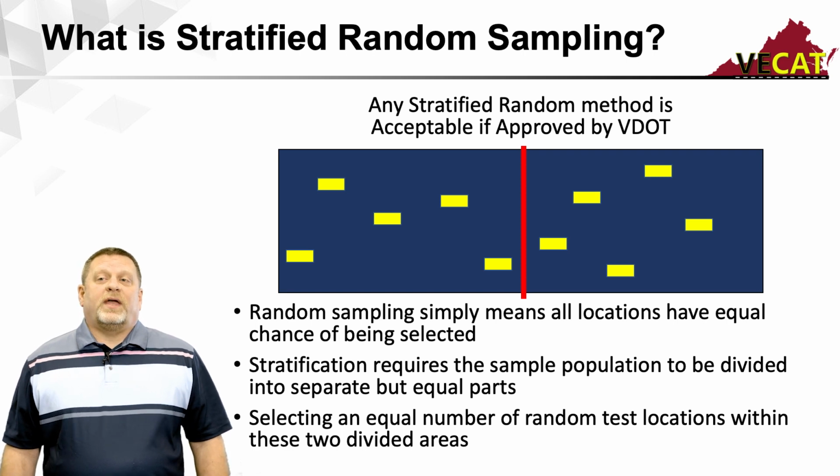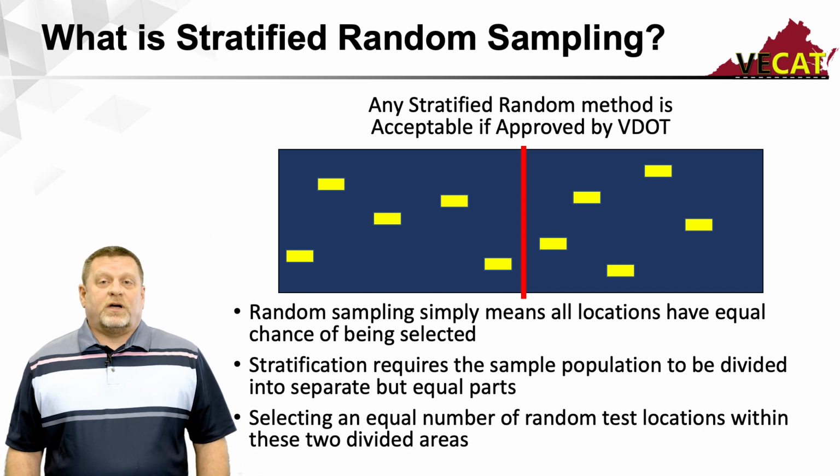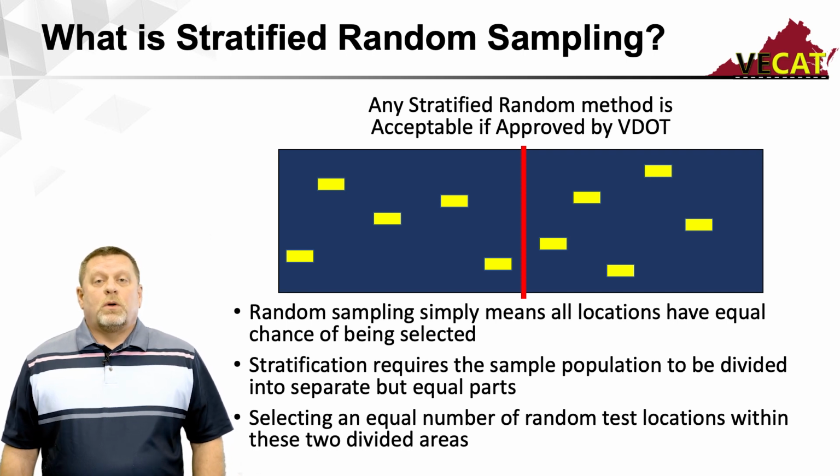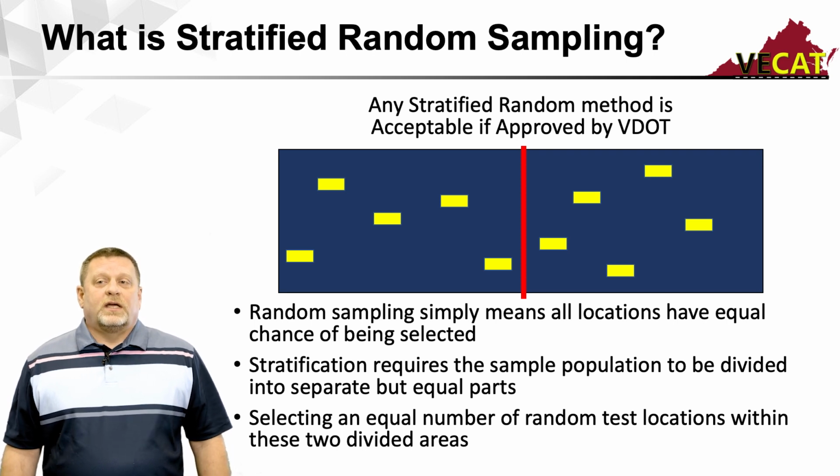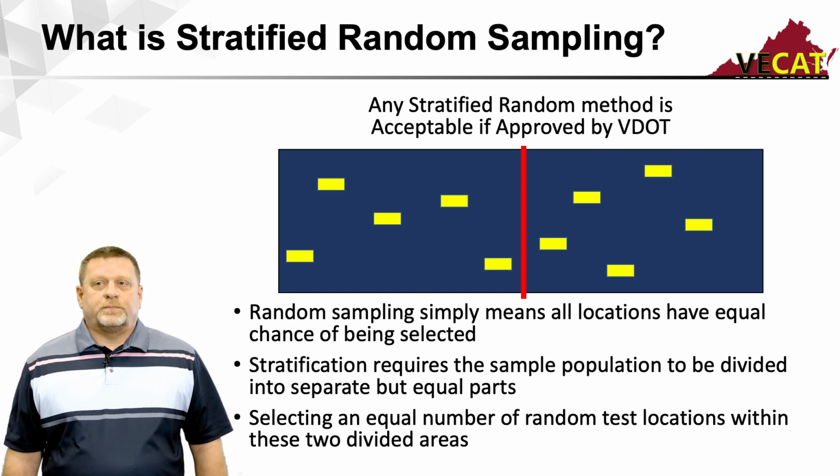So from that, we had 10 readings that we were going to take total. If we're breaking it in half, we're cutting this down to 150 feet. We want the first 5 readings to come out of the first 150 feet and the second 5 readings to come out of the second 150 feet, so that the total 10 readings is encompassing the complete 300 feet of pavement that is the actual control strip.